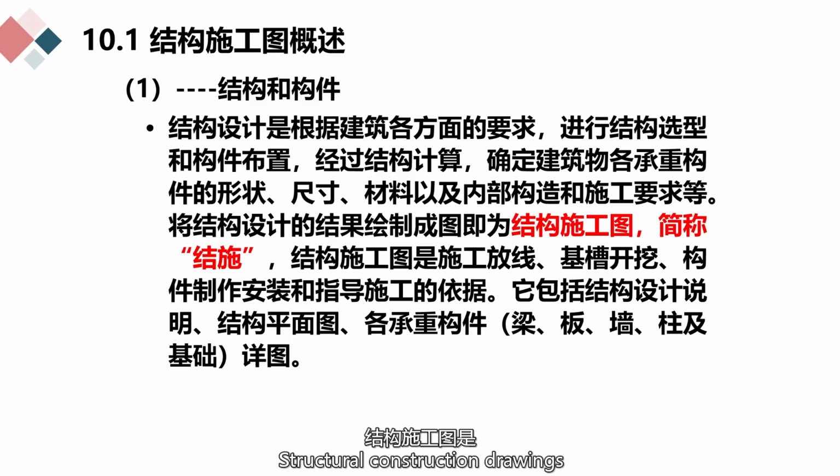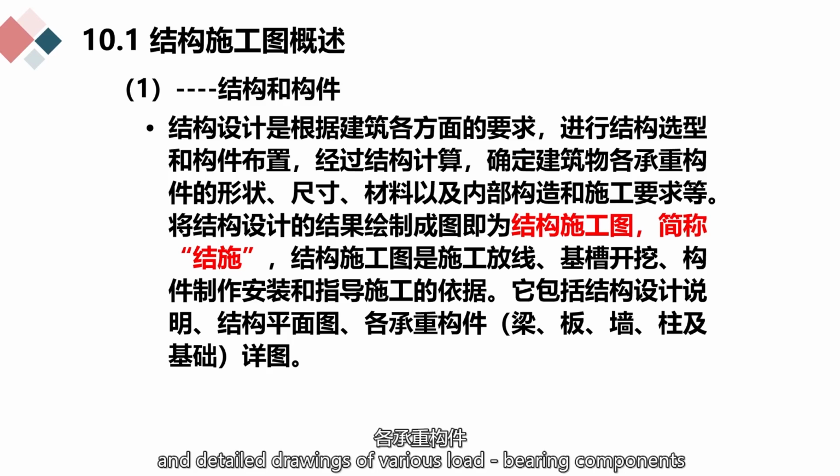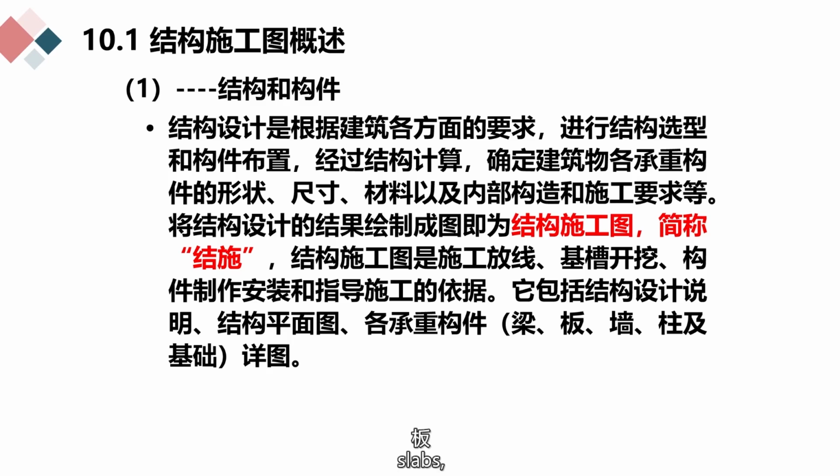Structural construction drawings are the basis for construction, setting out, trench excavation, component fabrication and installation, and guiding construction. They include structural design specifications, structural plan drawings, and detailed drawings of various load-bearing components, beams, slabs, walls, columns, and foundations.